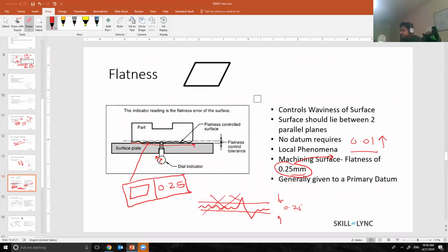So in the first week, all I knew is I had to work on mounts and steering systems. So I went through the previous drawings that were there for the mounts. FCA has been making cars for the last 100 years. So I went through the drawings from the last 4 or 5 years for the mounts and steering systems, and understood, okay, generally if it's a flatness, we give a 0.25. If it's a position, we give a 1 millimeter tolerance. And that is how it works, highly based on industrial experience.